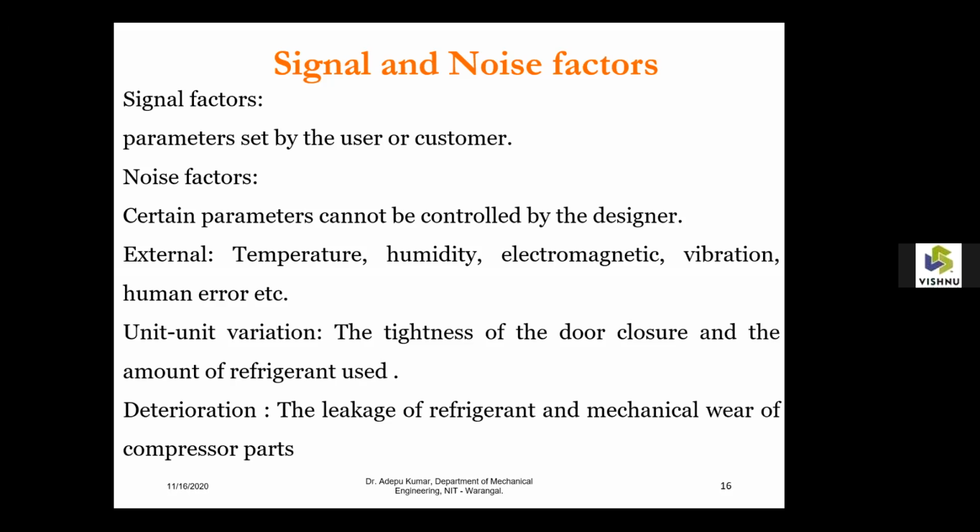Similarly, humidity is also one of the factors. During the welding process, humidity plays an important role. More humidity leads to porosity in the welds. That's why humidity is a very important factor. At 60% relative humidity, there will not be any voids during the welding process.